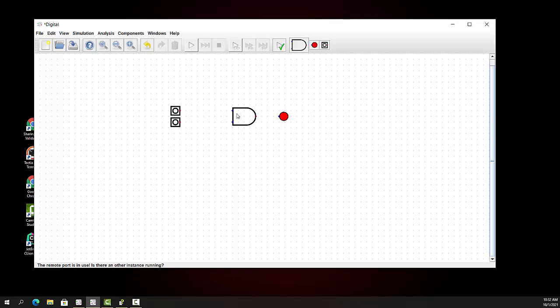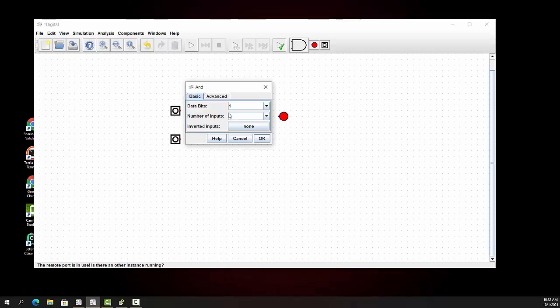And again, the way that they're connected is highlight it and move it to the left. Is these little buttons right here. This one is a two-input gate. And let me show you how to make it three. I'll click on it, or I can just right click on it. And you see data bits, and the number of inputs is, I'll make it 4. All right. And then advanced rotation, I can rotate it around using a wide shape.